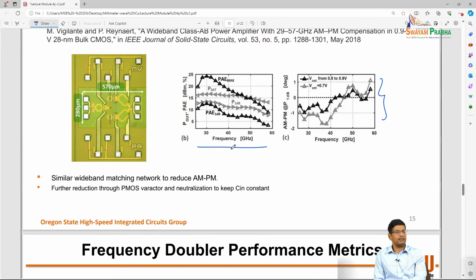So you can try things like exciting the PA with large impulse responses and looking at transient simulations to see if the output of the PA dies down. Those kinds of simulations are sometimes helpful to tease out common mode oscillations or oscillations that occur in large signal impedance modulation conditions. You can think of an impulse as a very wideband input, so you are providing a large input across a range of frequencies. So if there is an oscillation mode that can occur, the PA can latch on to that, right?